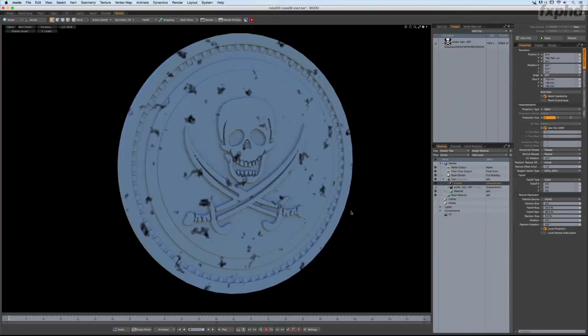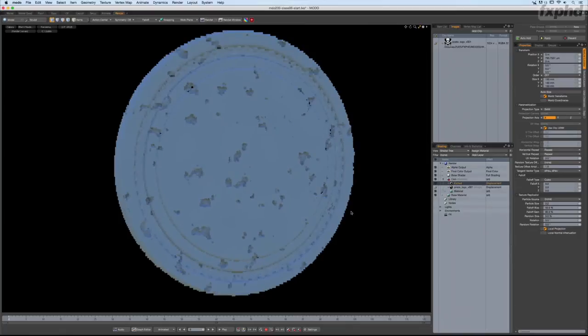And now you're going to start to see some problems jump into your scene pretty quickly once preview updates. Now, everything has grown. If you look very carefully, the size of my coin has been pushed out because now we're using that displacement engine to physically move the geometry on our meshes. In the previous week, I think we talked a little bit about bump maps, which is really just a rendering trick. Well, with the displacement map, we are physically moving geometry in and out, and it turns into real geo upon render.